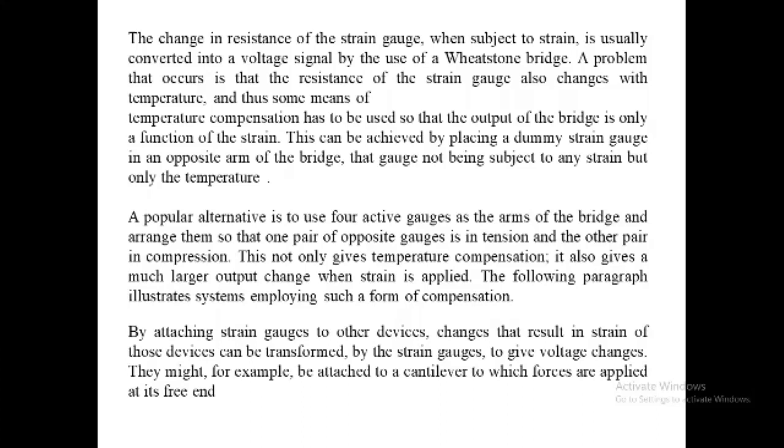Strain gauge bridge circuit. Basically, the strain gauge bridge circuit shows the measured stress by the degree of imbalance and uses a voltmeter in the center of the bridge to provide an accurate measurement of that imbalance. This arrangement is considered a quarter bridge. There are two more arrangements, half bridge and full bridge configurations, which give greater sensitivity over the quarter bridge circuit. Still, the quarter bridge circuit is widely used in strain measurement systems.